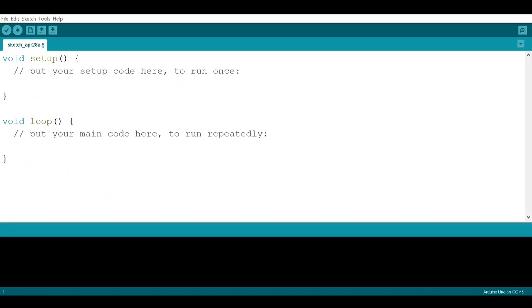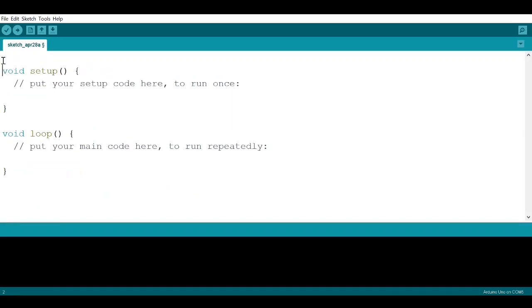And now let's have a simple small code. Let's try and make our Arduino LED blink so that it's perceivable to our eyes. So let's give an interval or a delay period of say 0.1 seconds. So let's start off by declaring a global variable. So const int, declaring a global constant, and let's call the variable name pin, give it a number 13.